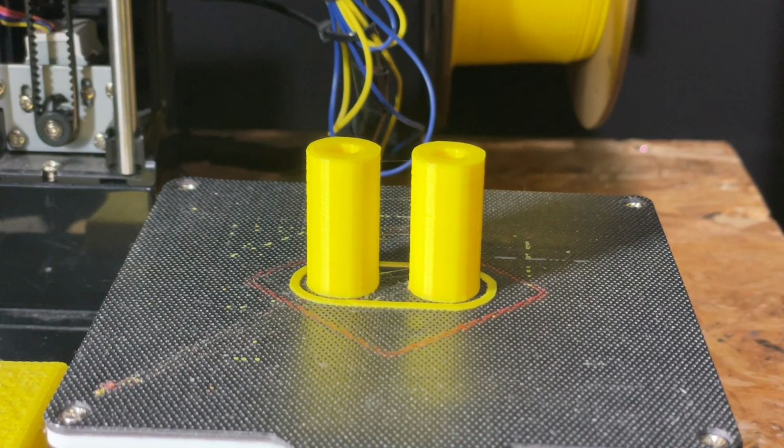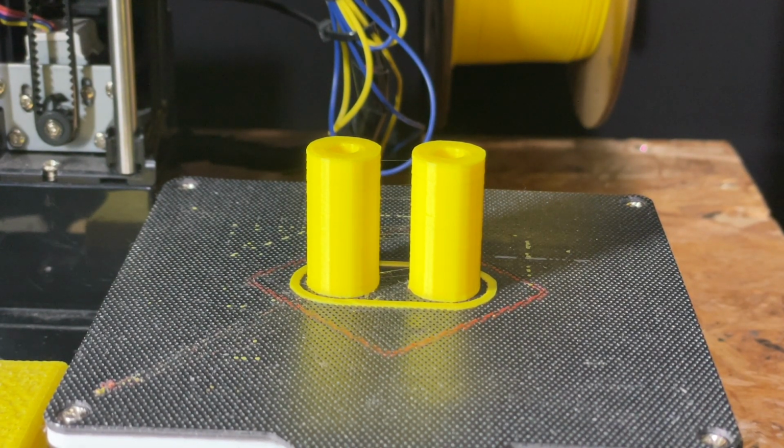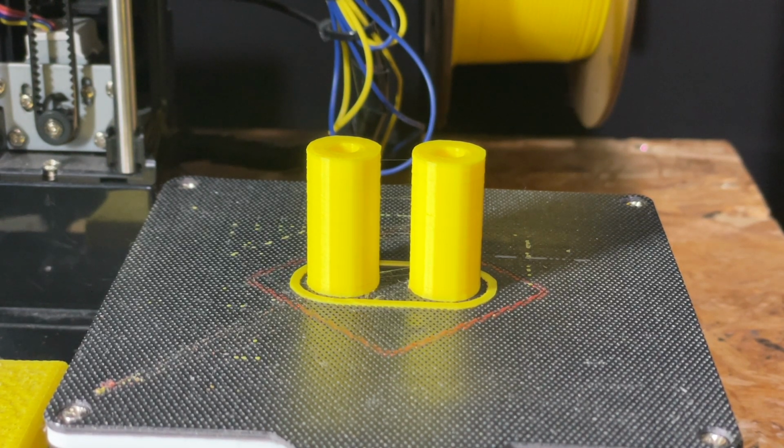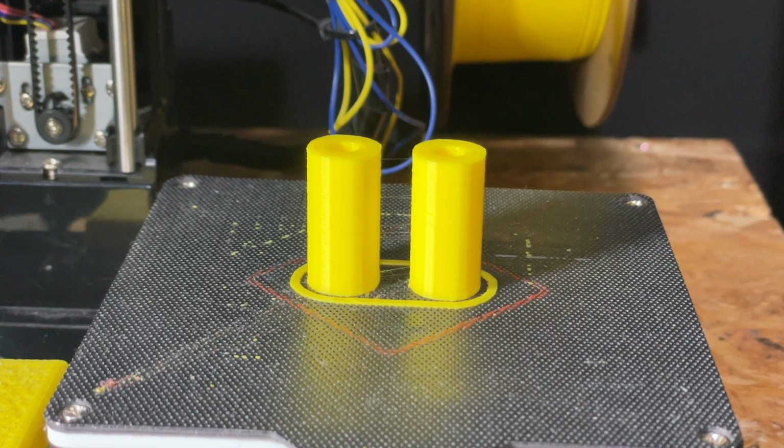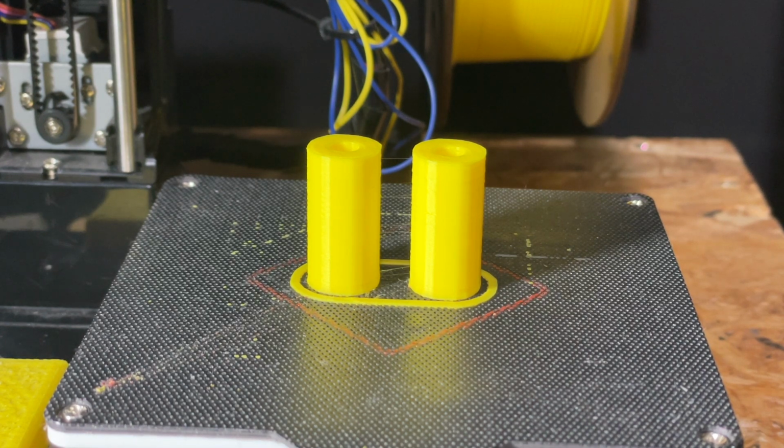Oh, now you can see the two printed out, and I'm really happy with the way it's printed out. It's amazing. I've made the skirt 1 millimeter high, which means about 5 layers if you're using 0.2 layer height, because if you don't make the skirt thick, it will be difficult to remove. Before, you can see on the bed itself that there's the red skirt and other skirts behind. I wasn't able to cleanly remove them because they're too thin. That means printing something over the top of them to then lift them off. It will work, but it's a waste of material.